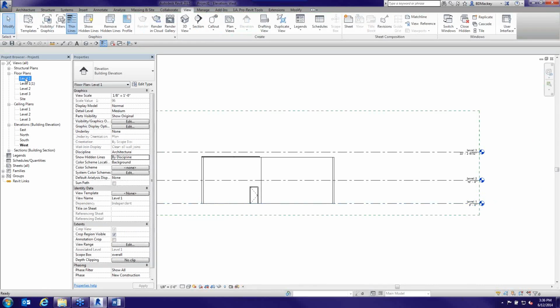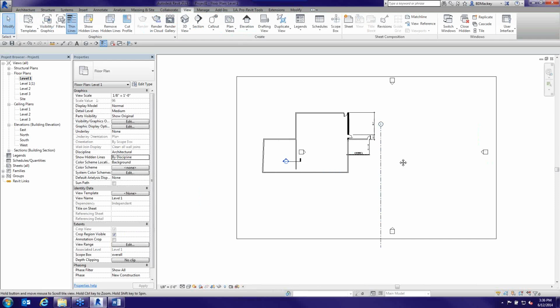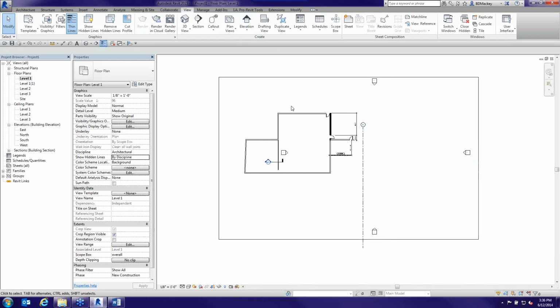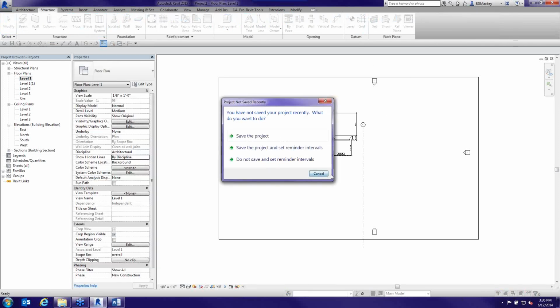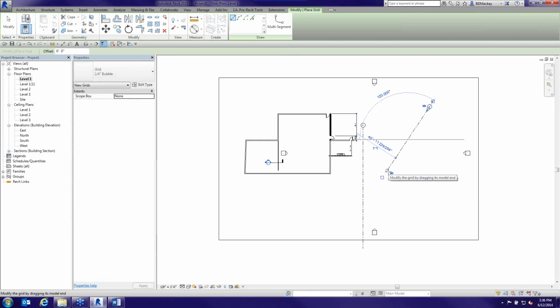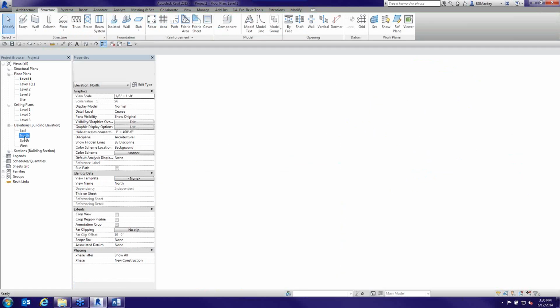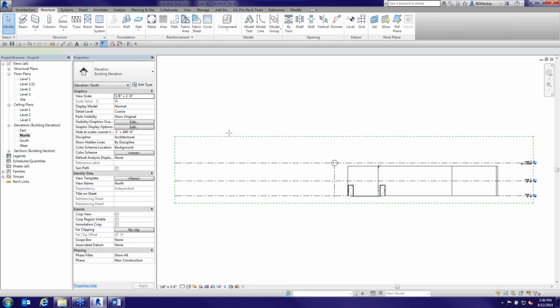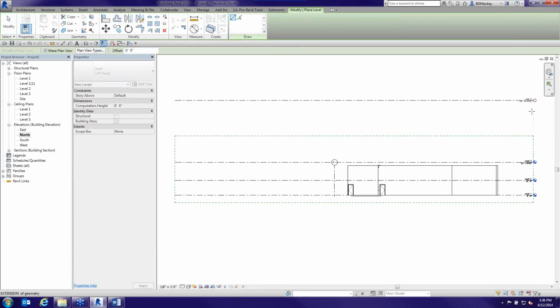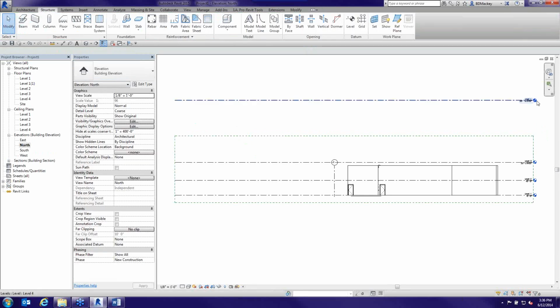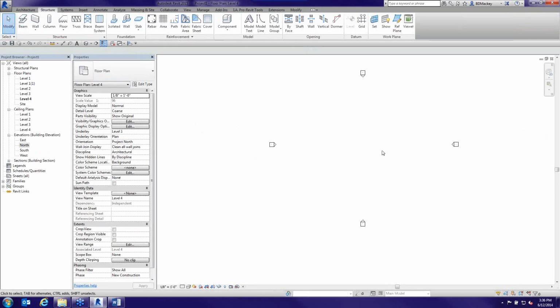The other thing, and this is more for you structural engineers out there, how many times have you had grid lines? Let me go create a grid here real quick. And somebody created all of these grid lines, right? I've got these radial grids coming on here, and this is great. I've got all these beautiful radial grids, and maybe we even had a curved grid on here. And then the project develops, and somebody comes in and adds a new level. So there's this new level up here, and I go to this new level, and I can't see any of my grids, right?